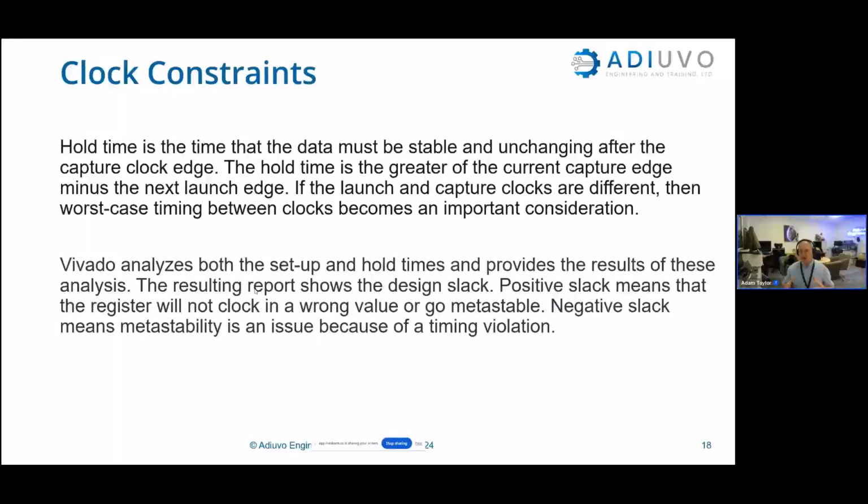So just to make sure that we're aware, obviously, of hold time, we're going to make sure the hold time is making sure that the data is stable after that clock edge. And we're going to need to be very carefully considering that the launch and the capture clocks are different, particularly to make sure that we get the hold and the setup time.